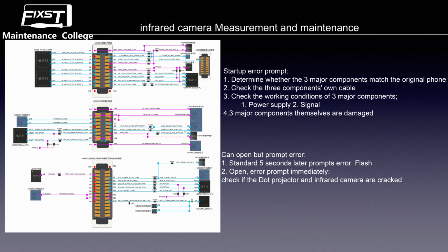It's like if the CPU is cracked or broken, we also cannot repair it. Okay, now talking about the second problem. The phone can open the Face ID interface but prompts the error. First, it stands for 5 seconds and then prompts the error.